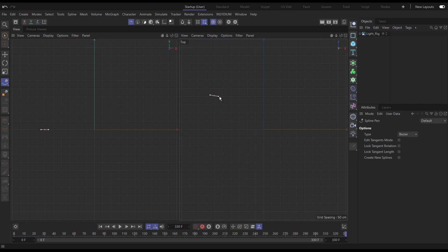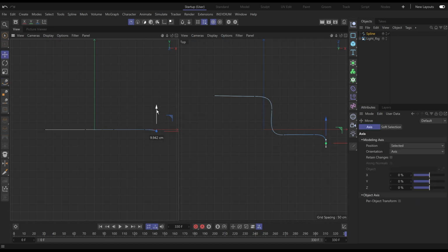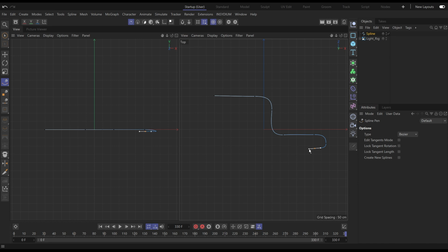So let's create that Z shape. We'll create the first point, second point, bend it down and around. Let's push that just a little bit further over. And we'll get to the apex of our first corner. Then if we go to the left-hand view panel, we can click E and start to drag this down to add that verticality.